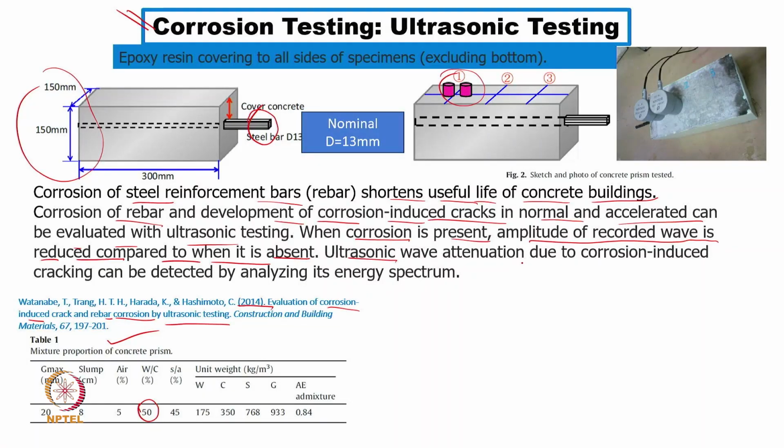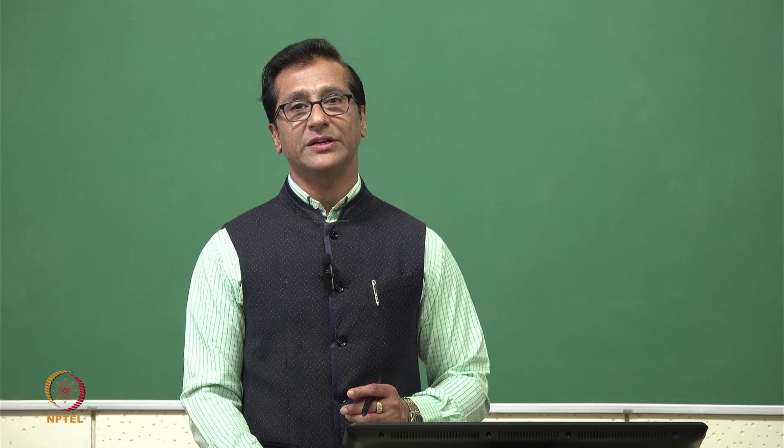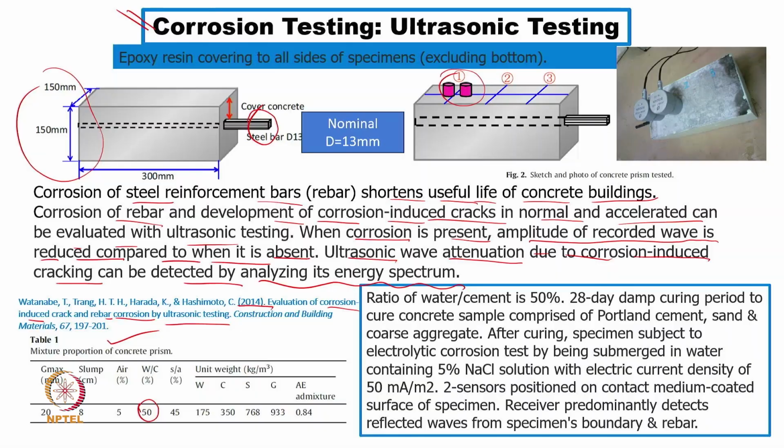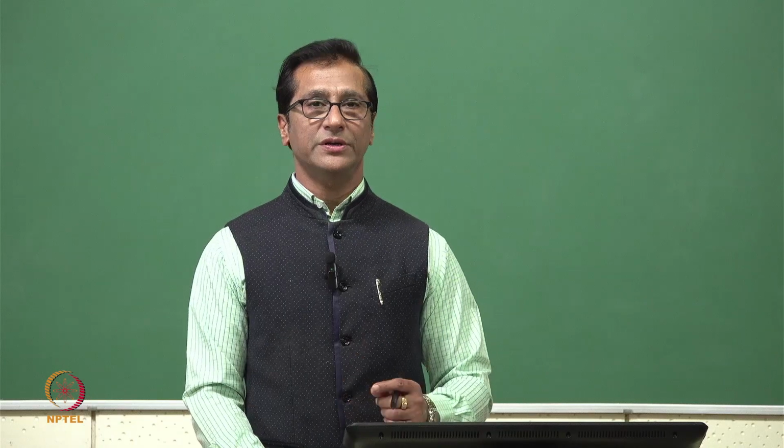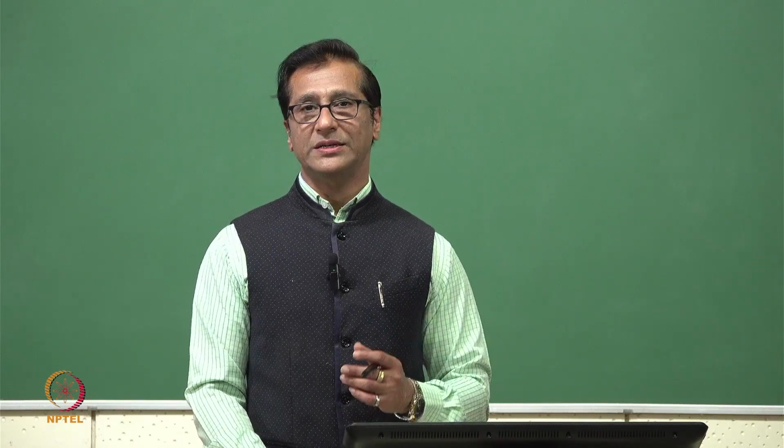So we say ultrasonic wave attenuation, the reduction due to corrosion induced cracking, can be detected by analyzing the energy spectrum. This is another method to connect with energy spectrum. Now in this case, whatever has been done, as I say, the water to cement ratio of concrete is 50-50%. They tried for 28 days, because every concrete has some sort of curing time, and then they used a 28 day curing period, so that concrete samples get formed, particularly in Portland cement.